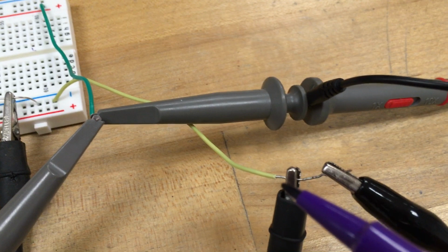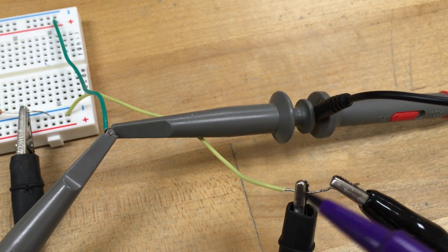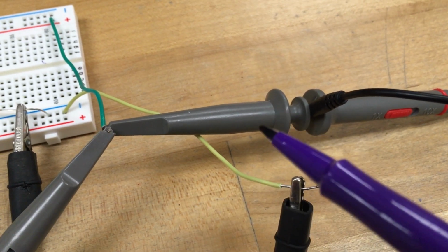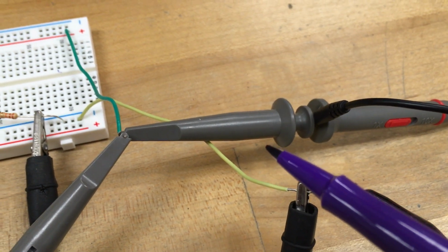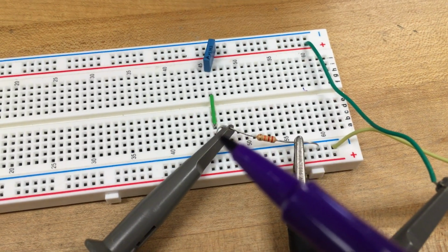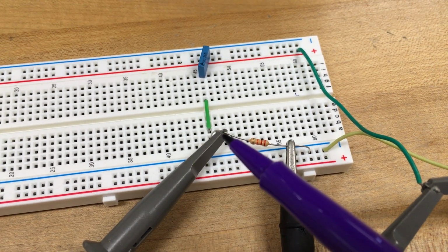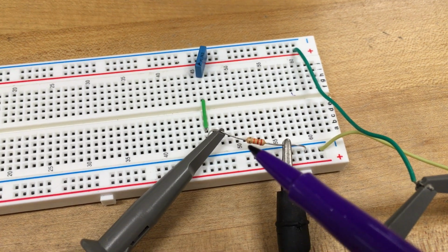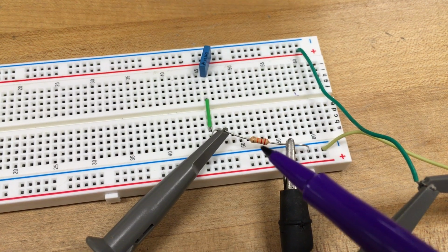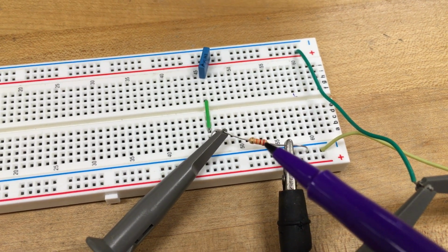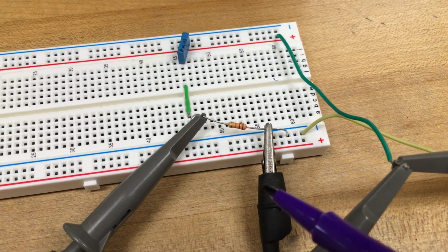So essentially we're putting that probe, which is probe number 2, so the blue trace in our oscilloscopes, right across that power source. So it's just reading out whatever voltage signal the power source is putting into our circuit. And then over here, we've got the other probe, so probe number 1, which is going to be the yellow trace, across a, let's see, we've got red, orange, so that's 22,000 ohms, so 22 kilo ohms of resistance sitting here. And we're measuring the voltage difference across that thing.